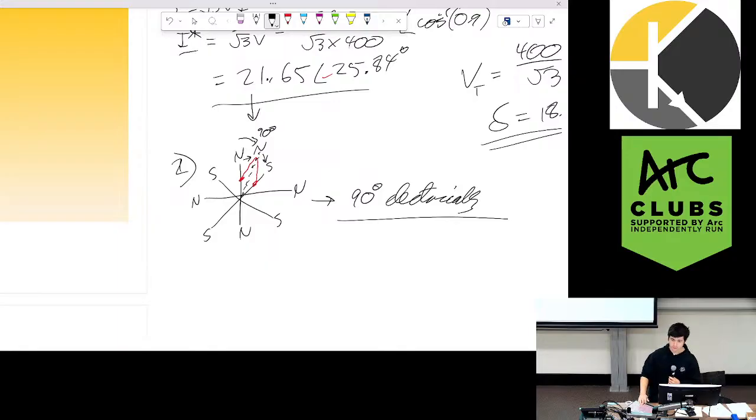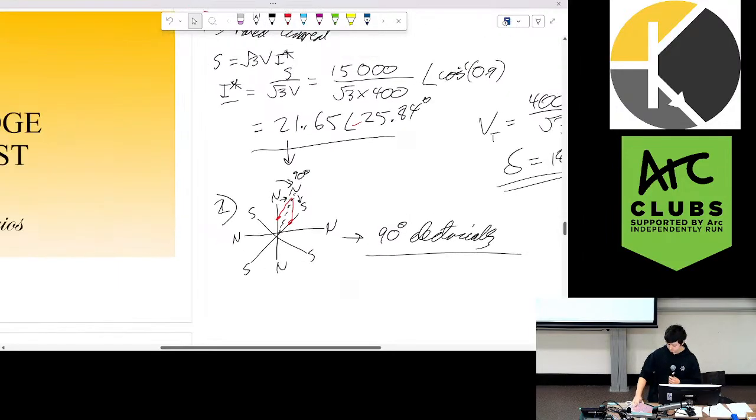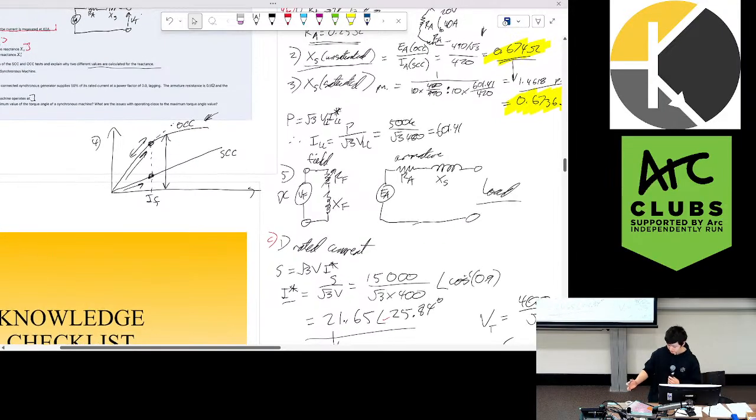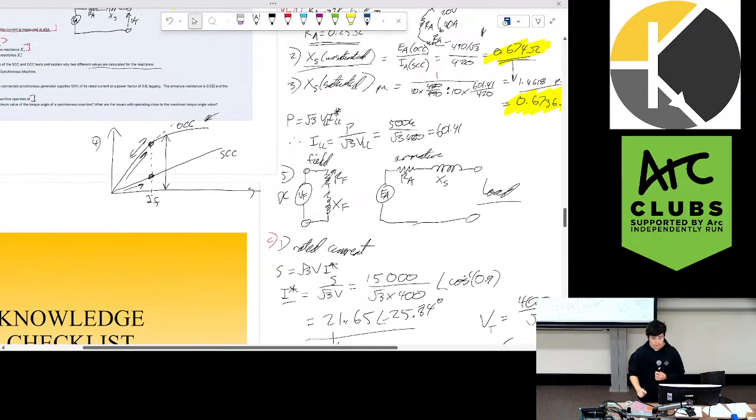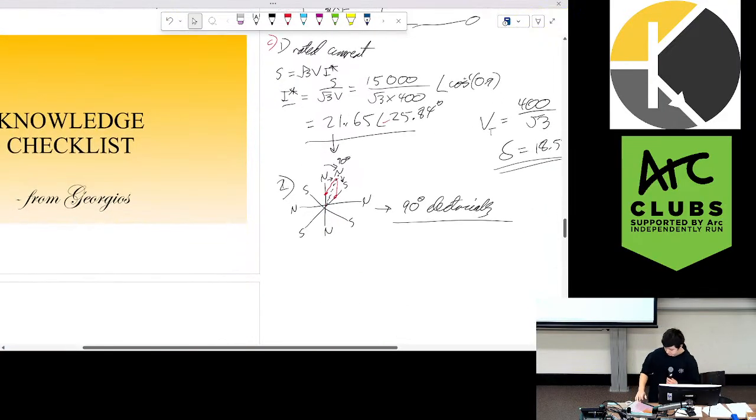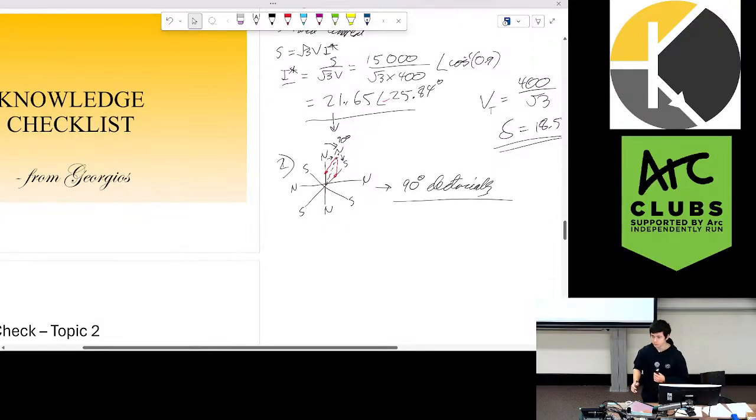The reason being we want to avoid pushing it to such a large torque angle. Why we don't want to operate near it is to avoid torque fall. We don't want our motor to stop working, right? It gets pretty costly because then you would have to continually start it up and constantly use an induction machine as a backup, and at that point, what's the point of using a synchronous machine? Just give it more voltage. Yeah, all right.